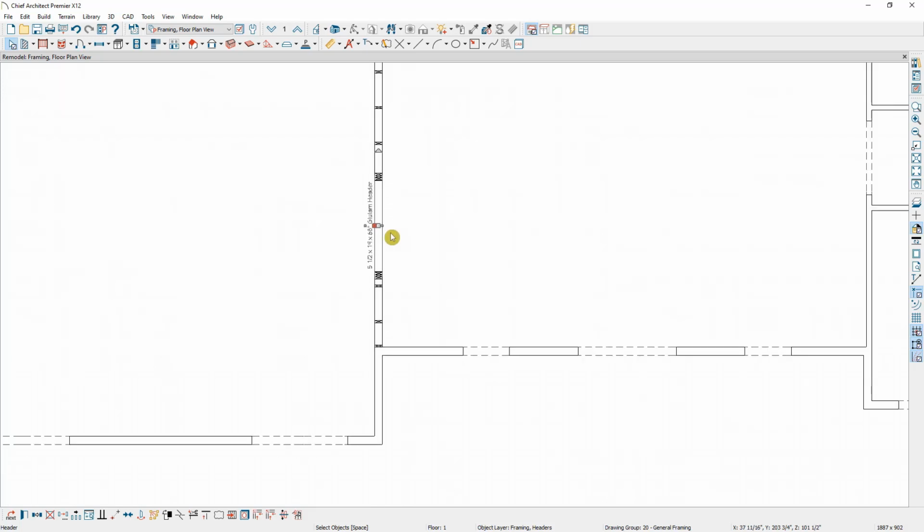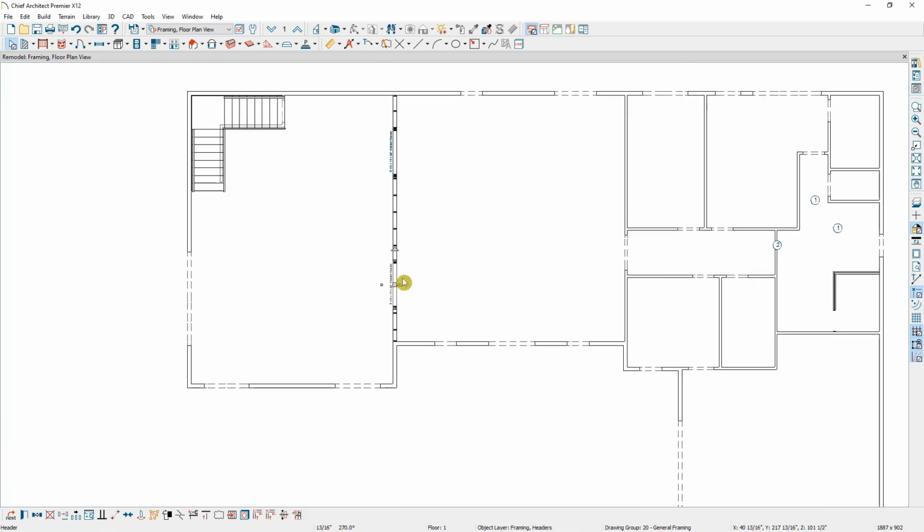If we want to frame only the walls that we've added into our addition and remodeled room over here, we can select those walls, and then once again press that frame for selected objects button. Let's do that for our addition as well. I'm going to select our wall tool and then hold shift and select all of these walls just to make sure we get the walls underneath the stairs. Then hold control and select this one and press the framing button.